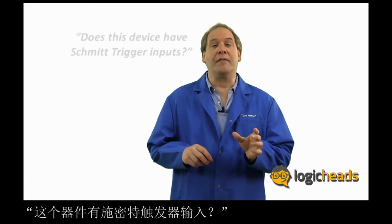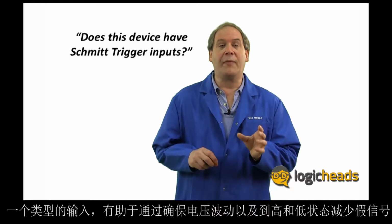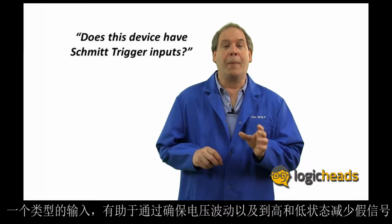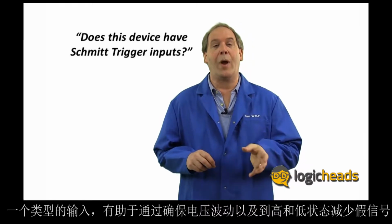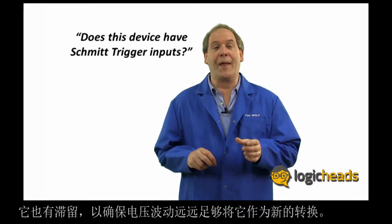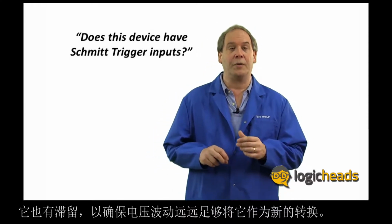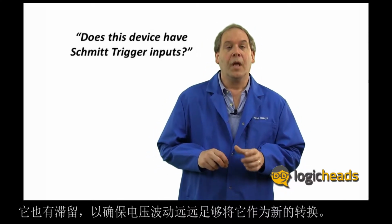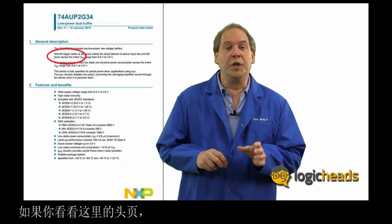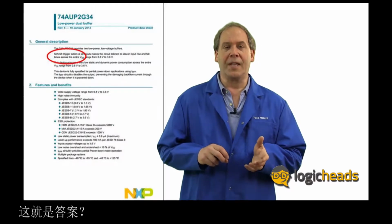Does this device have Schmitt trigger inputs? A Schmitt trigger, of course, is a type of input that helps reduce noise by making sure that the voltage swings well into the high or low states. It also has hysteresis to make sure that the voltage swings far enough one way before it swings back for a new transition. If you look right here on the front page, you will see that it says Schmitt trigger actions. Is this the answer?